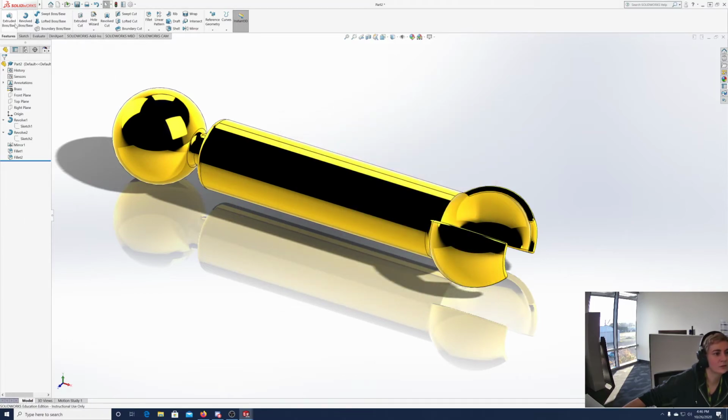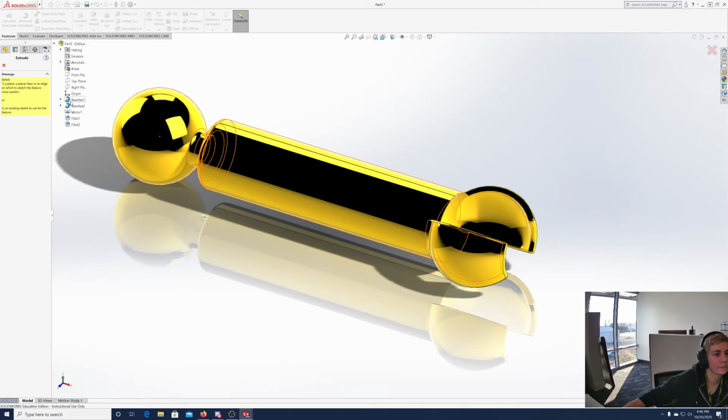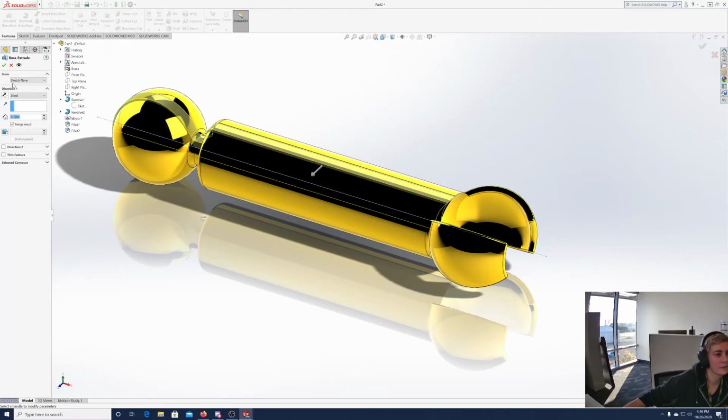I think it's just if you extrude something, let's just use sketch 1 here. Okay, yeah, so this is a draft angled extrude. If you click this little sort of cone shape here, it's not really a cone, but you can extrude something so that it angles outward or inward instead of just being a straight extrusion.